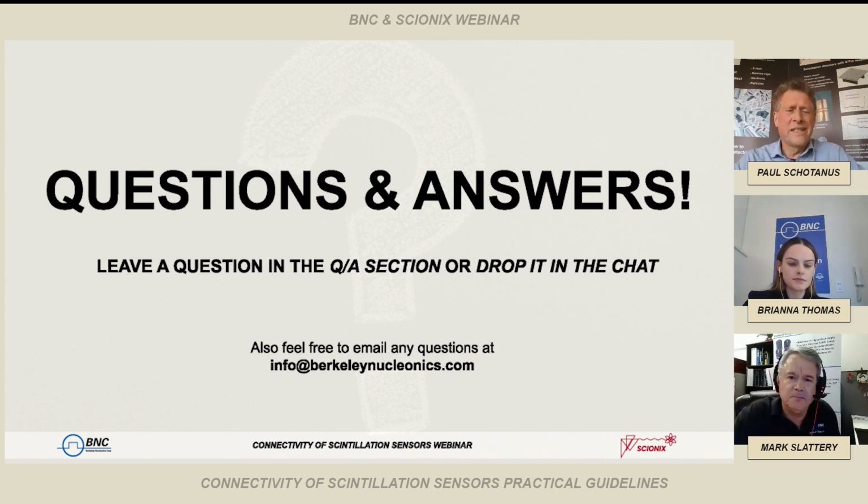But my answer is that in many applications, silicon photomultipliers will replace classic photomultiplier tubes, and are at the moment replacing them. The process has started already. But there are applications where silicon PMs cannot replace classic photomultiplier tubes, for the simple reason that silicon PMs are noisier than old-fashioned photomultiplier tubes, especially at elevated temperatures. If you have an application where the temperature goes up to, let's say, 60 degrees or so, then the use of semiconductor silicon PM technology is much more challenging. But then it depends totally on what you want to do.